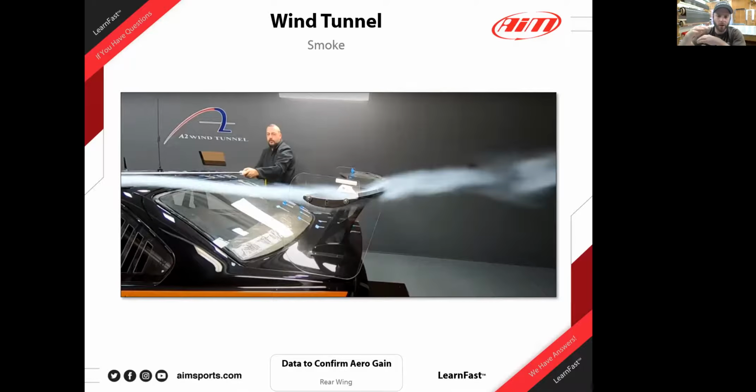But that wing is one of those where the center is not as steep as the sides. And I think what was happening, you can sort of see it in the smoke a little bit, you're getting separation off of the underside. So the gurney flap is sort of delaying that separation. Without the gurney flap, I think the wing was performing really badly, where the gurney brought it into a position where it was performing better, but it added way more drag than any other gurney flap on another wing. So that's one of those where it's hard to say specifically. That particular wing wasn't great, I'll say, but it wasn't bad. But yeah, you can do stuff to optimize it for sure.